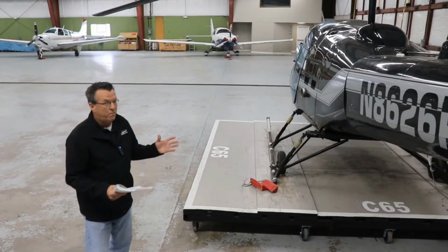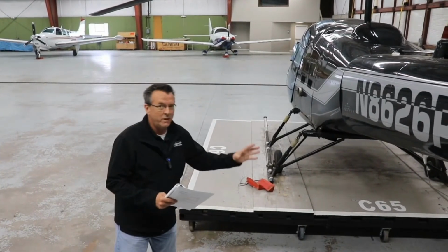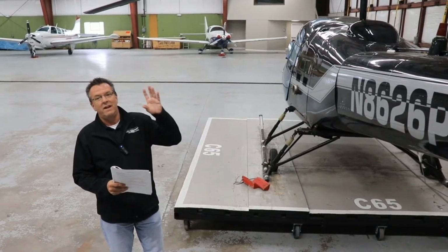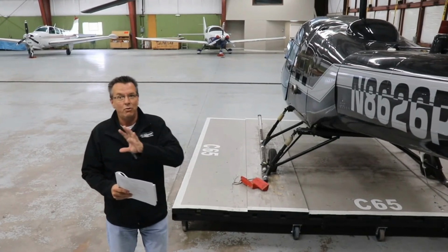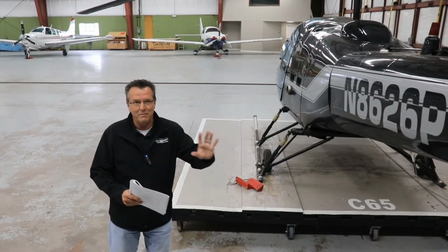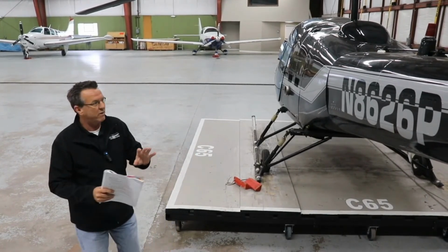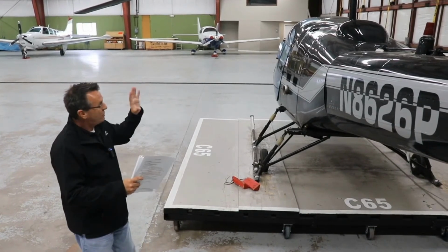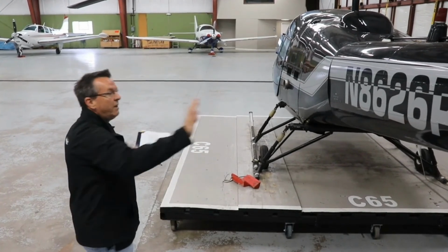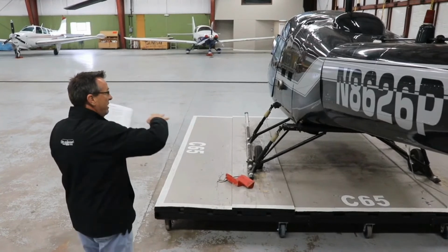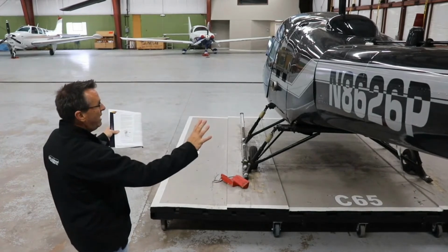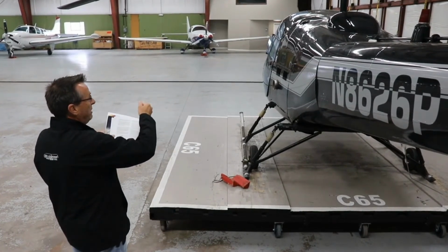So to sum it up, people screw up all the time between translating tendency, effective translational lift, and transverse flow effect, okay? So also know for your check ride preparation, those three get confused many different times. They get jumbled together with people on a check ride. So on this one, this is translating tendency. And just think of it again one more time. That tail rotor is pushing. It has tail rotor thrust against the tail boom. So the aircraft is going to want to drift to the right during a hover. So depending on what you're flying, you're either going to have to hold in left cyclic.